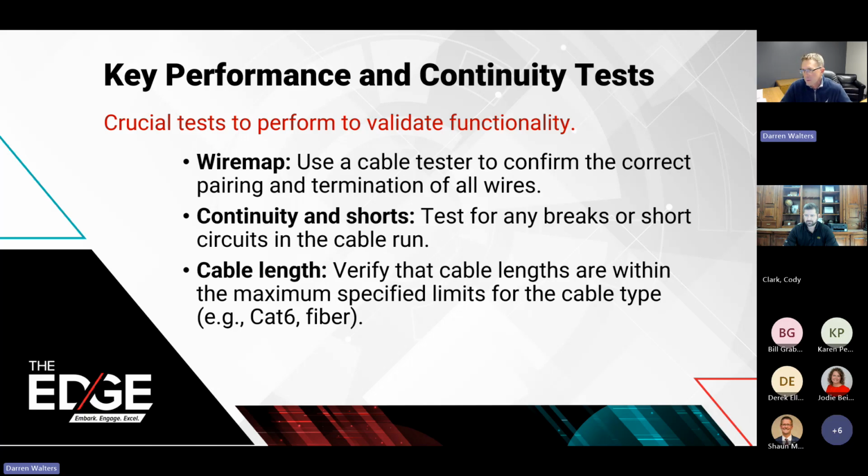We got connectivity from end to end. So what it does, we will test wire map, which makes sure that all the pinouts are okay and in the right order, and we understand and didn't forget our color code. So basically, it's wire map to make sure that there's nothing crossed up or in the wrong color slot.